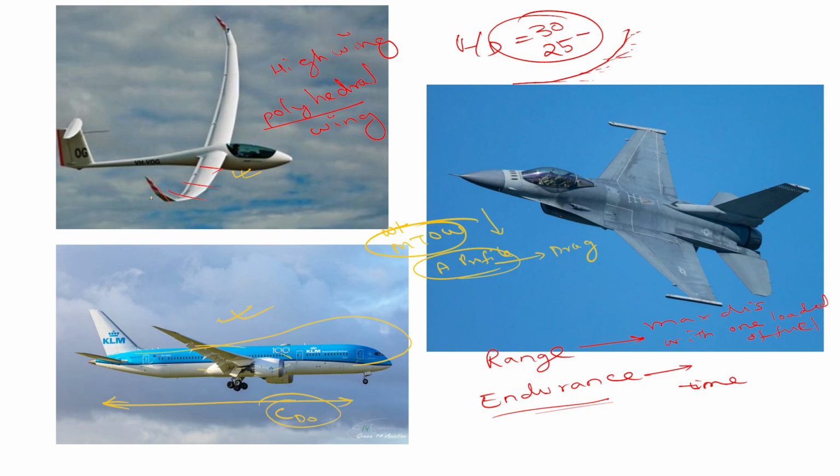And then one more doubt: while designing a wing, we find a Reynolds number. But for the fuselage, the Reynolds number will be a higher value, because while designing the wing we take the chord length, but while designing the fuselage we take the entire length of the fuselage. Very simple. You were asking why it happens so, right?